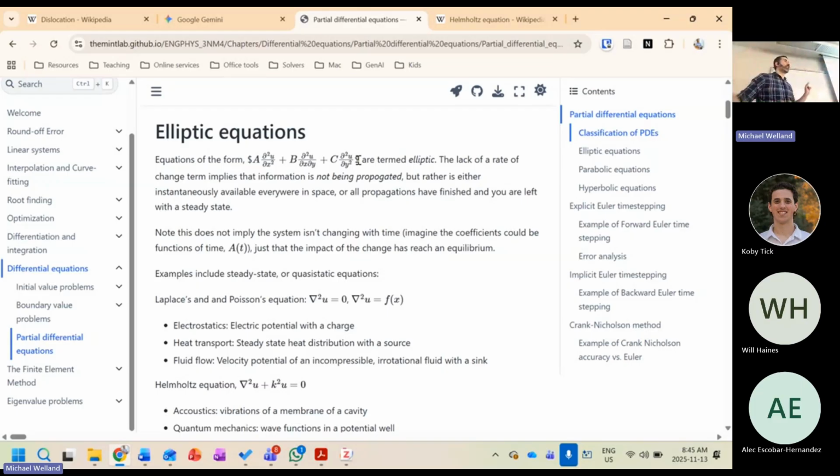The problem is that those waves are happening so fast. Speed of sound, what is it, 300 meters per second over the scale of 15 centimeters? Super fast, to the point of not really being relevant. That's why we can do this quasi-statically. And this is elasticity in a nutshell. We don't have to worry about those waves because they're happening so fast. This is also a trick for how you get around the stiffness problem.